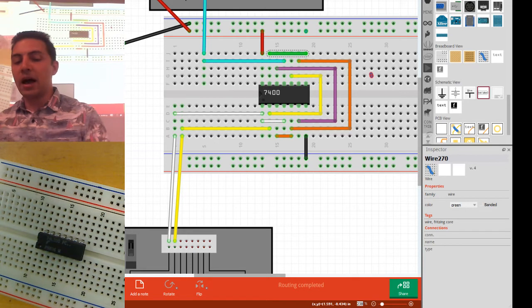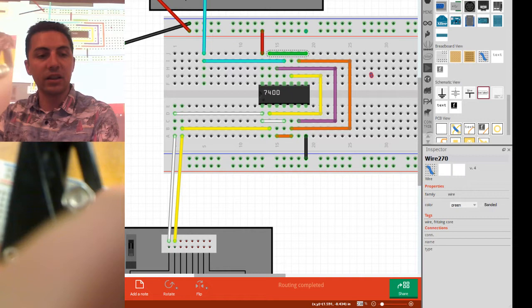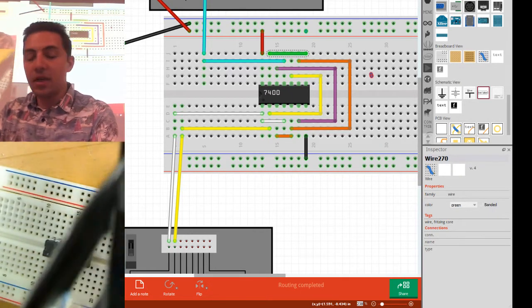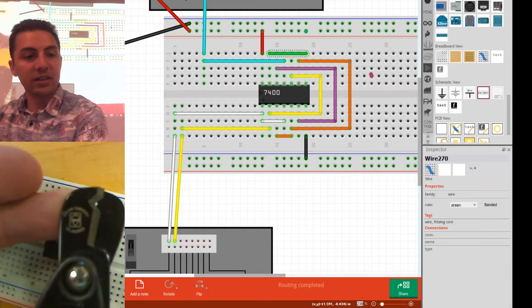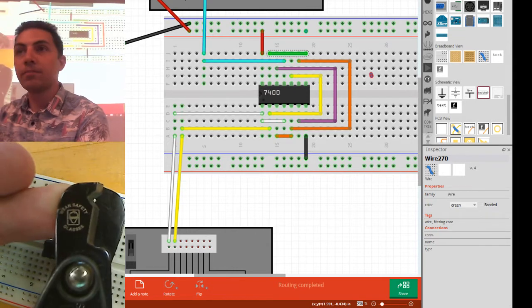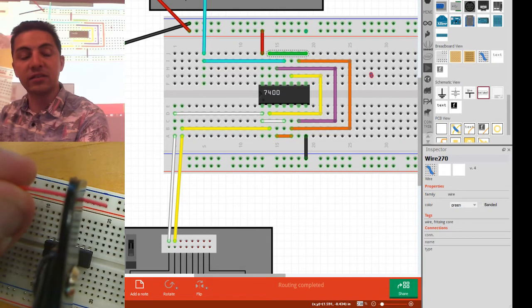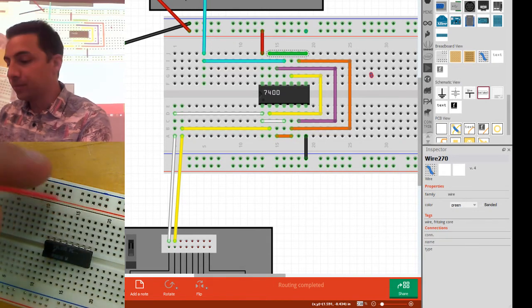It doesn't really matter, but these kind right here, these are presettable. There is a little nut combination that will allow you to set the gauge of that little hole. Can everybody see that you can see light through that hole? That is specifically designed to be thinner than this insulation, but thicker than the wire.